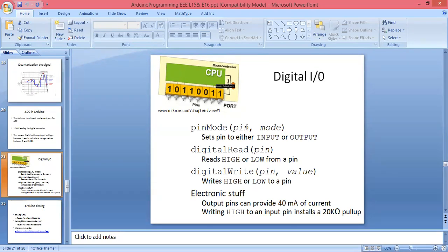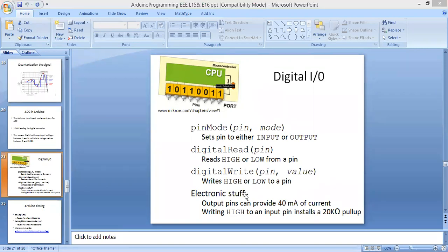What we do in the setup function will remain until the life cycle of our program, or until we reset the board. So we can assign any pin as input or output in the setup function, so that in our program we can use that pin as input or output.